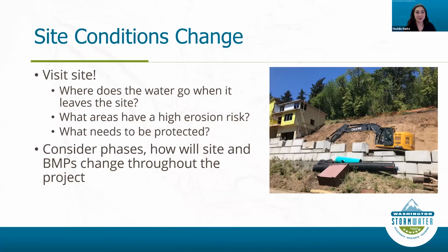So my first tip to you is to visit the site. Site conditions change, and visiting the site is a great way to get a visual on it. Especially if you can visit when it rains, that's fantastic. When you visit the site, you want to consider, where does the water go when it leaves the site? What areas have high erosion risk, and what needs to be protected?